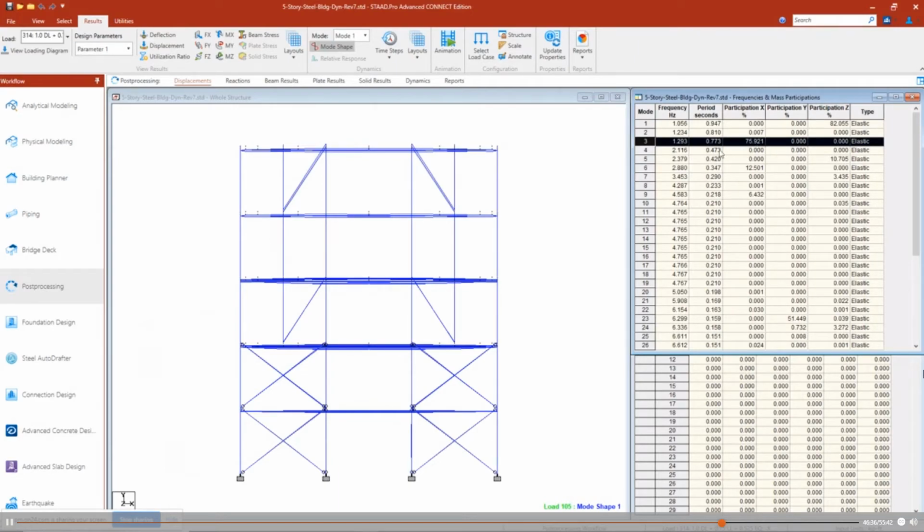So this is going to be a big one there for us for the X direction. For the Z direction, we actually accelerated the structure in the X direction, but if we had accelerated in the Z direction, we would actually get a higher participation at about 1 cycle per second, right? So you can see based on these modes how all of this plays out on your structure.